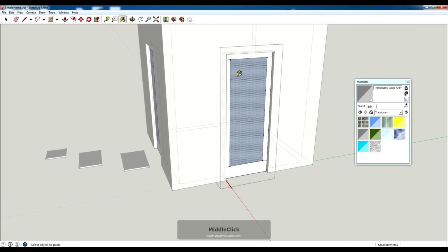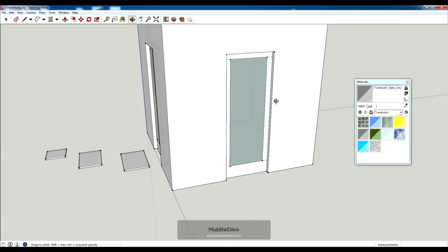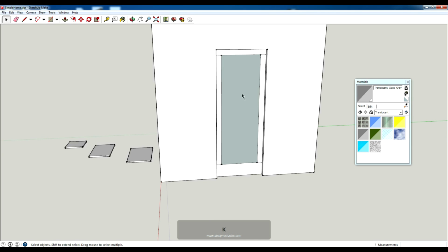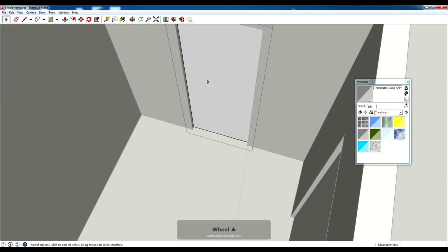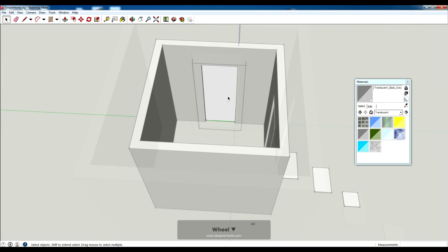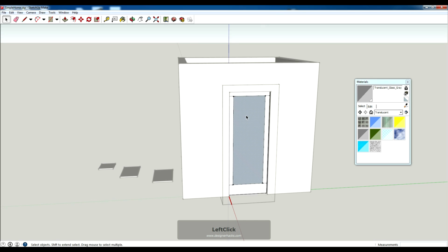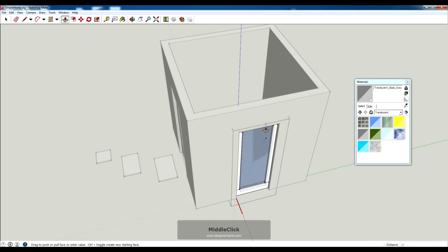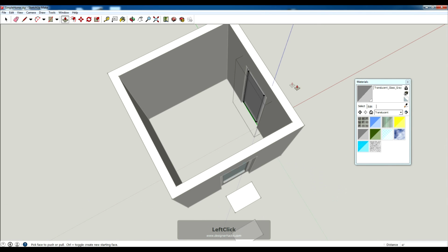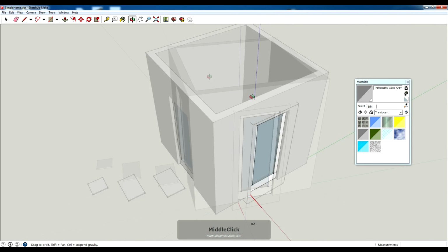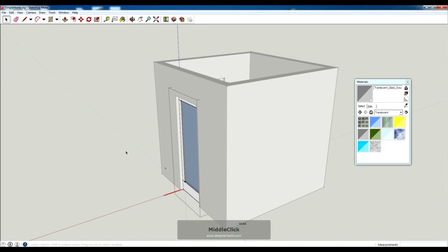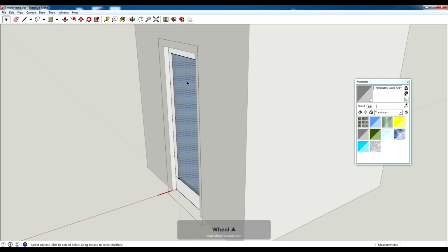and you can see that it changed it to translucent, but for some reason I can't see through, and that is because this other face didn't translate through. So what's going to be helpful here is I'm going to copy this face and then extrude it in. So you can see now I have an extruded face here.